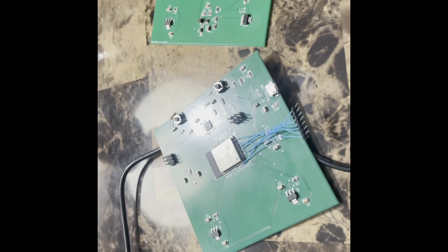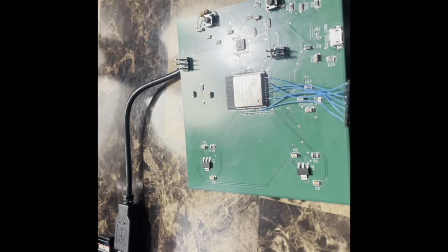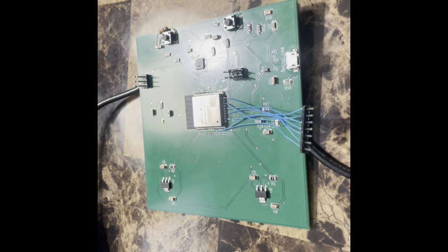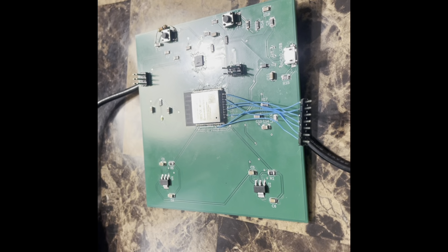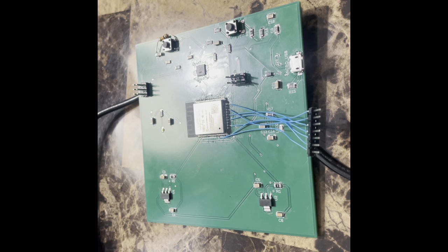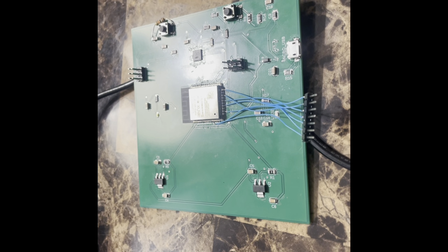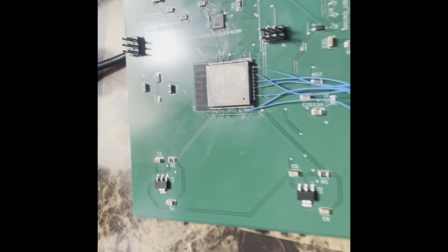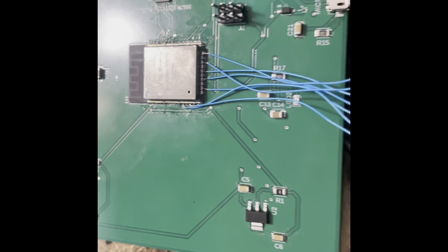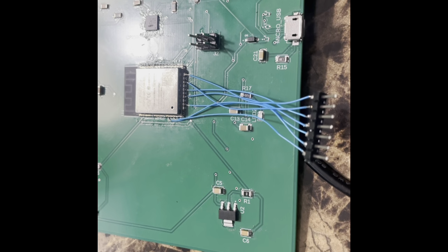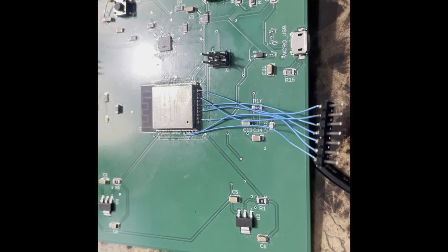Specifically, here we can see that we had to incorporate a bunch of extra GPIOs, and that happened because it turns out we were missing quite a bit of pins for the display. So we had to solder a bunch of extra wires to GPIOs. All of those wires are going to just extra GPIOs soldered to pin headers so that we can use more additional pins for the display.